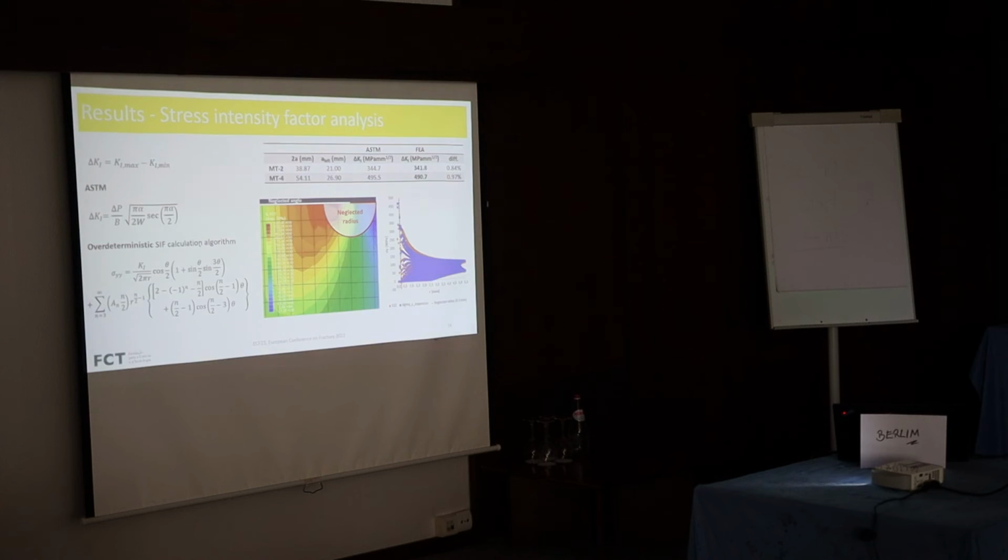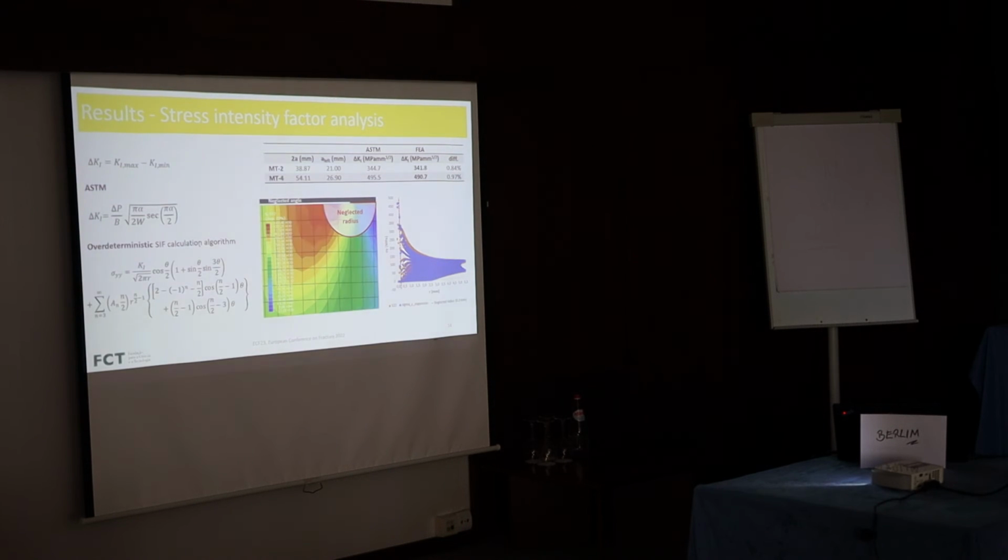In terms of the stress intensity factor analysis, we compare our numerical results with the theoretical ones, using the over-deterministic stress intensity factor calculation algorithm that is presented in the ASTM standard. And if you look, the results are very, very similar, with differences of 0.84% and 0.97%.